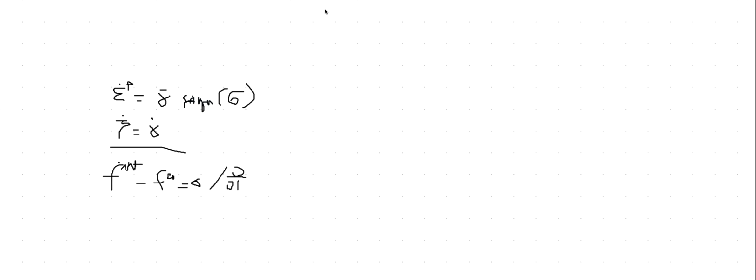This amounts to saying I have df internal over dd times d dot equal to f external dot. So basically, this will be just the tangent stiffness, elastoplastic.